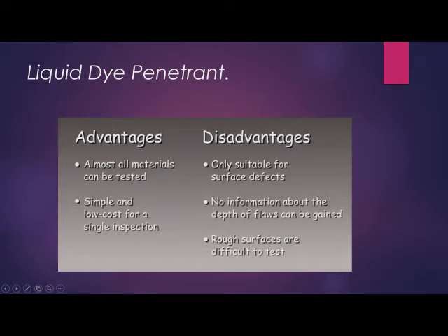For advantage and disadvantage of liquid dye penetrant. Advantage: almost all materials can be tested. Simple and low cost for a single inspection. For disadvantage: only suitable for surface defects. No information about the depth of flaw can be gained. Raw surfaces are difficult to test.